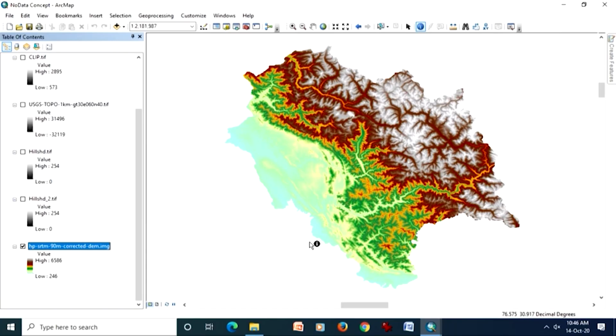Rest of the areas are mixing with the ground. That means the no data value. So whenever you encounter such problems, try to handle these things through no data. And as I have already told you, once the no data has been declared, that value is never used in any kind of calculation or estimation or statistics. So that value is always ignored by the software.